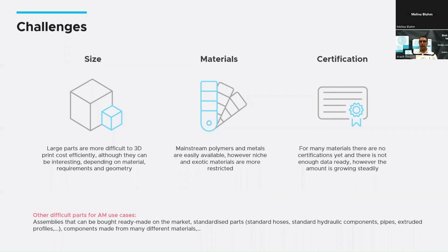On the material side there are also challenges. Of course, the mainstream polymers and metals are almost all easily available. But if you are going to niche or exotic materials, then the availability of these materials for additive manufacturing is more restricted. The other topic is the certification for the application of the materials. Many materials still do not have the required certification from industry, because either there's not enough data yet or it is still in the standardization process.